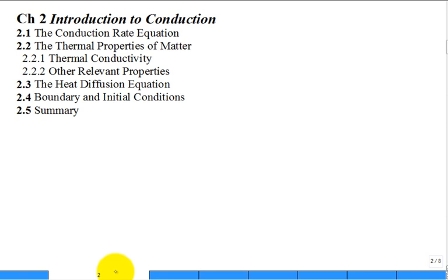All right. Introduction to conduction. What were the two big equations out of this? Well, q as a vector is equal to minus k, what is this del thing? Yeah, it's the gradient operator. So we talk about scalar fields, temperature scalar fields. We talk about a vector field for the heat flux. I should put a double prime on that, shouldn't I? Because that's a heat flux vector field. And that's the generalized Fourier's law.